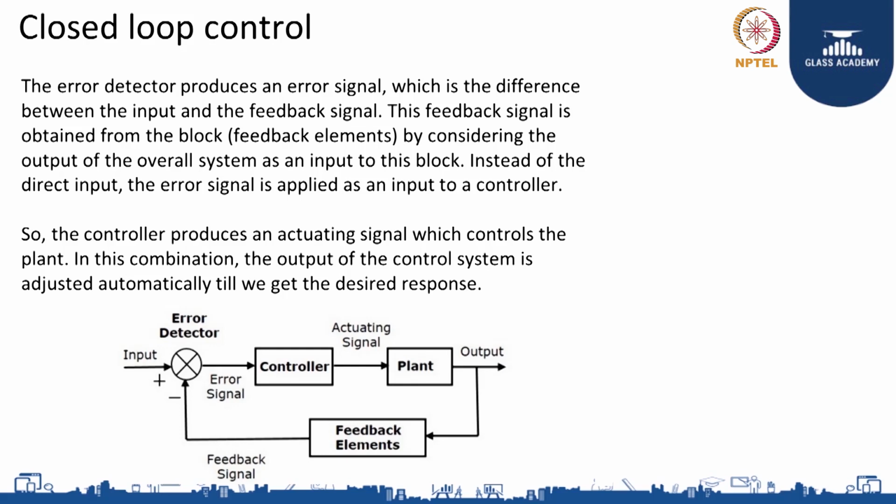So we measure this as an output from the system, and we compare the input with the output, basically by subtracting the output from the input, and the value so obtained is the error. Say for example, if you want to maintain 500 lux and we currently measure the illuminance level to be 400 lux, then 500 minus 400 would be the error, that is 100 lux.